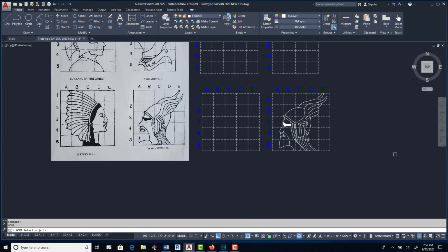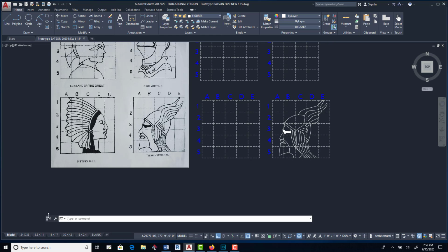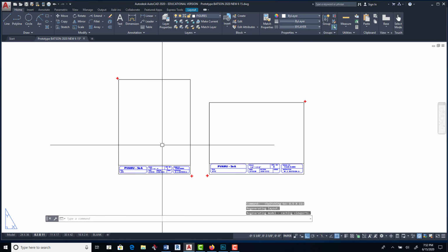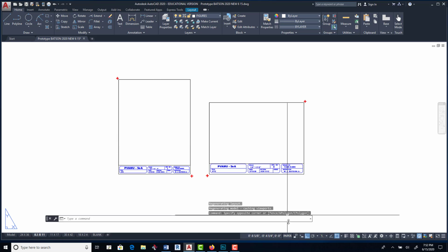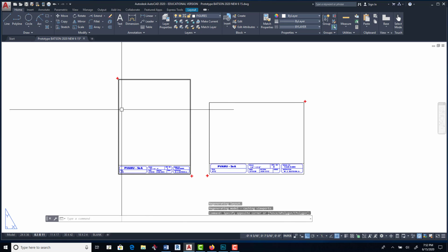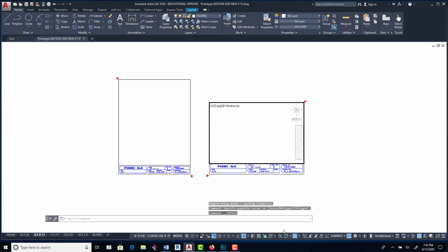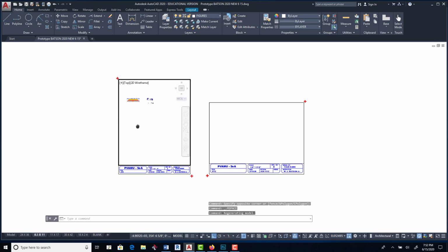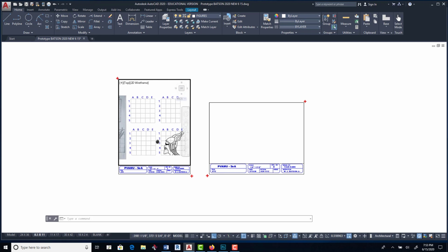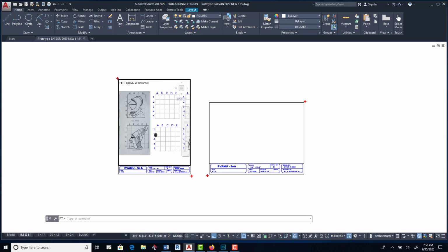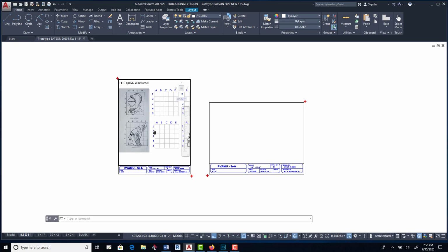So now there. Now, when you get ready to print plot, what you're going to do is you'll go to your 8.5 by 11, and you'll use your portrait, remember, and then you'll click on paper space and make that highlighted border. See, there's a border here. Now there's a border here. So now you can, there it is. You can zoom in there, zoom extents, or there it is, right there. So now, wow. So how far is that? That's pretty good, isn't it?